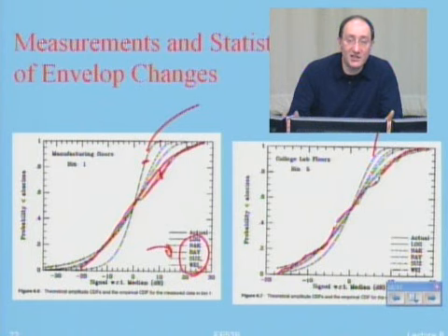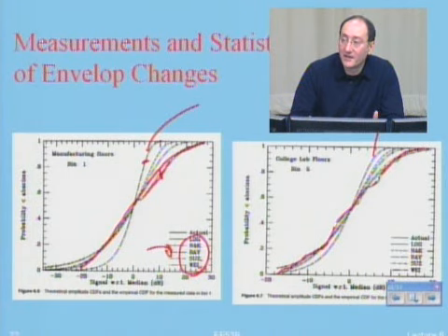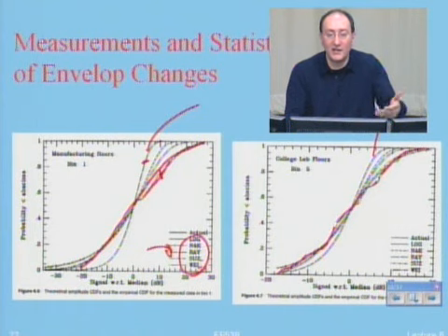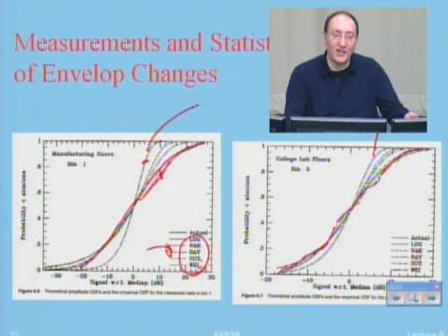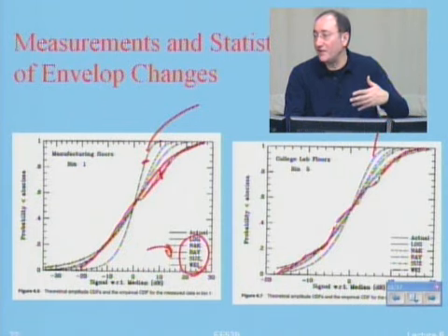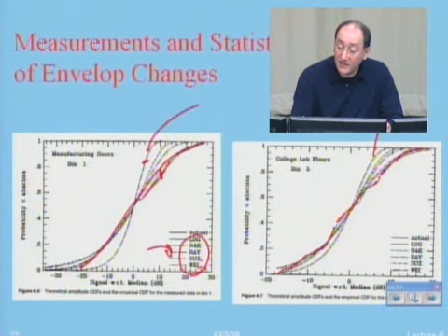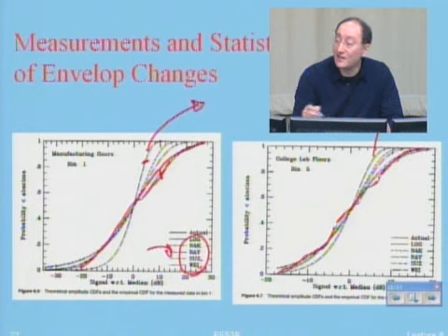We were using the widest bandwidth, but 200 megahertz is important for who? For ultra-wideband type of applications, because they have a minimum of like 500 megahertz. And when you go above a couple of hundred megahertz, behavior looks like ultra-wideband. You have many, many paths, and as a result, paths don't combine with one another. So you don't have variation in Rayleigh fading. Since that's the case, they don't fit Rayleigh anymore.